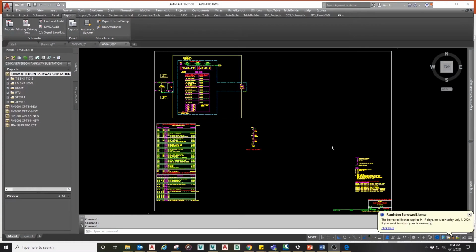Welcome to the SDA AutoCAD Electrical Training Module for schematic reporting. In this video, I'm going to illustrate how to run a cable from to report using the schematic reports. So under the Reports tab, I'm going to select Reports under the schematic ribbon.